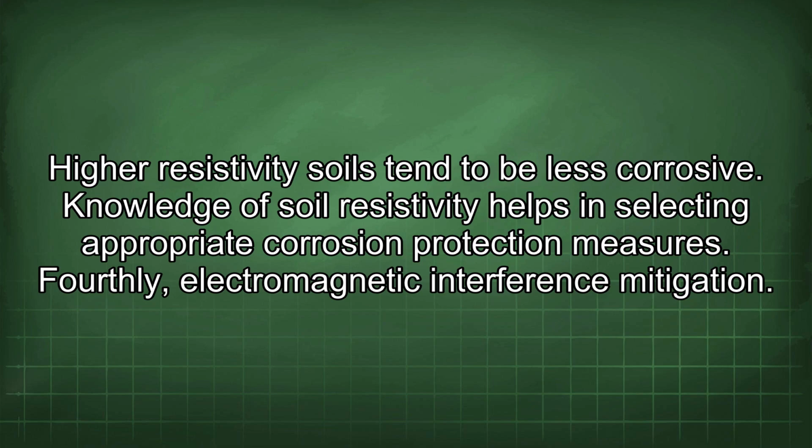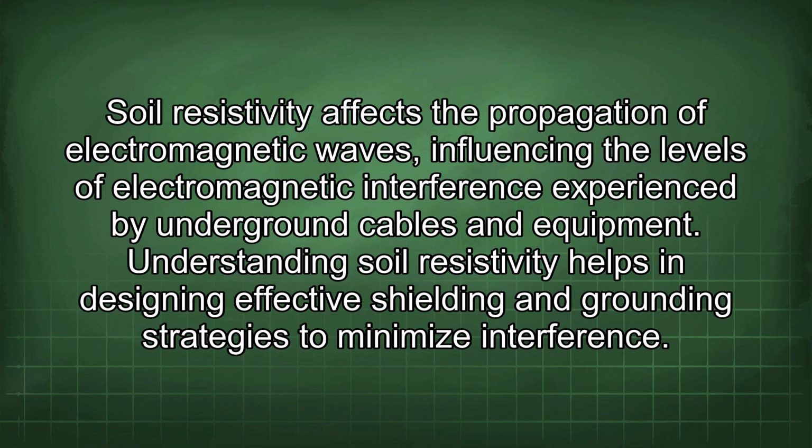Fourthly, electromagnetic interference mitigation. Soil resistivity affects the propagation of electromagnetic waves, influencing the levels of electromagnetic interference experienced by underground cables and equipment. Understanding soil resistivity helps in designing effective shielding and grounding strategies to minimize interference.